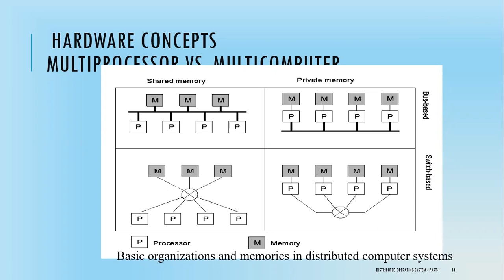To read a word of memory, a CPU puts the address of the word it wants on the bus address lines, then puts a signal on the appropriate control lines to indicate that it wants to read. The memory responds by putting the value of the word on the data lines to allow the requesting CPU to read it in. A write works in a similar way.